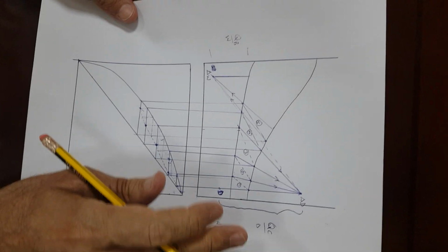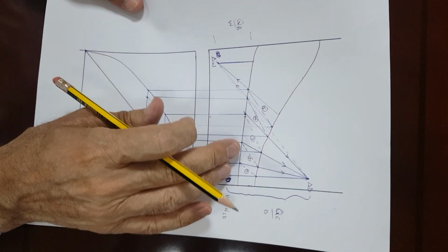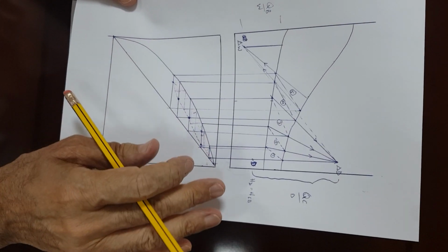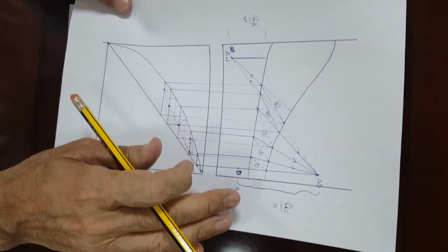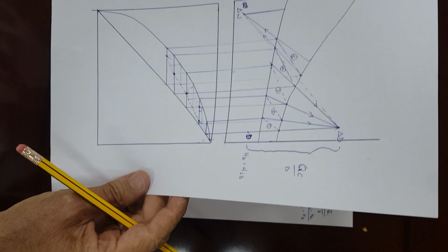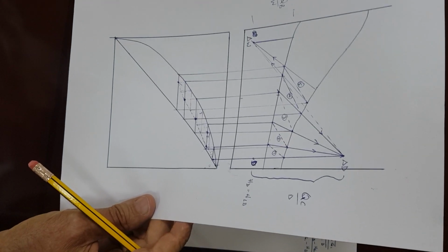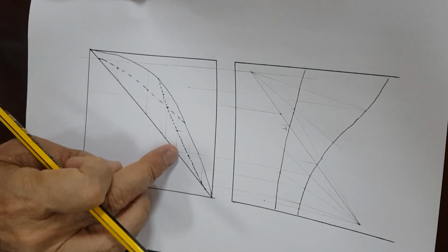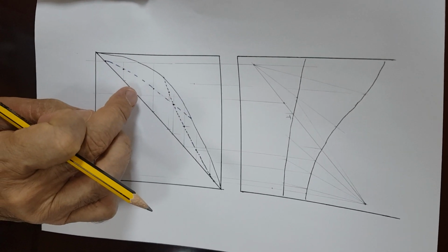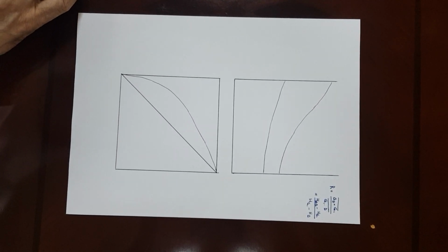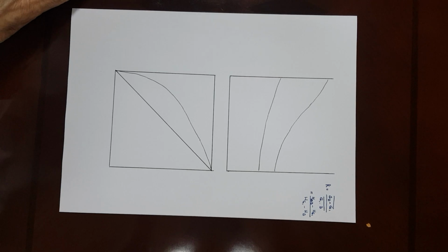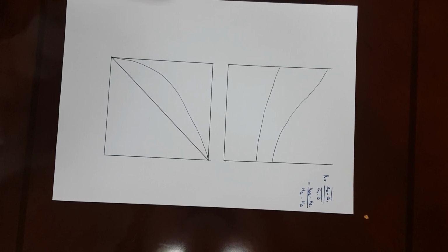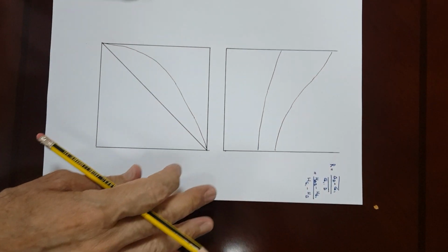The first method is using the enthalpy diagram along with the y versus x equilibrium diagram to develop the stages directly. And the second method is to develop the nonlinear operating lines for the enriching and stripping sections, and then you can use a method similar to the McCabe-Thiele stepping.